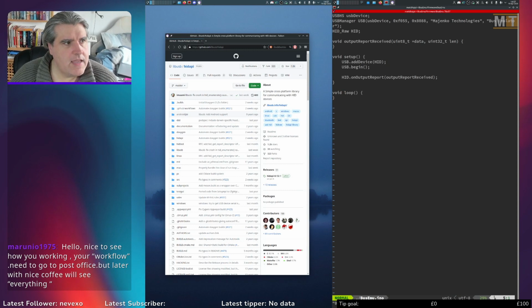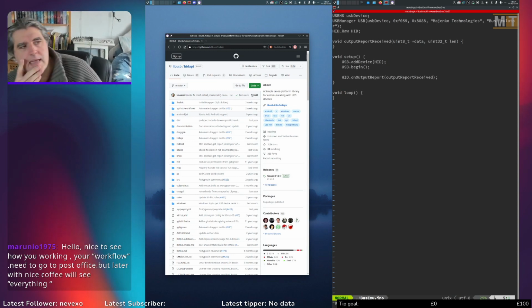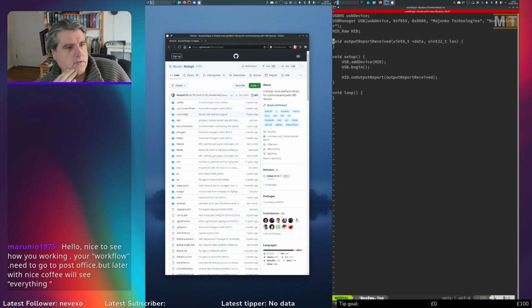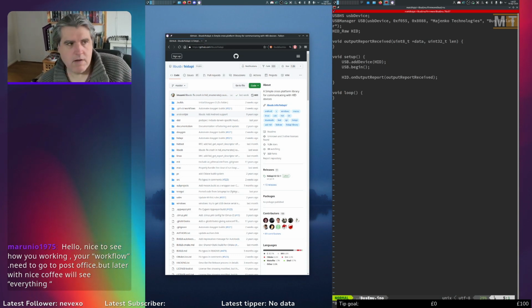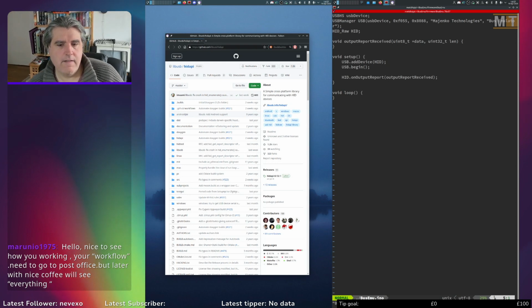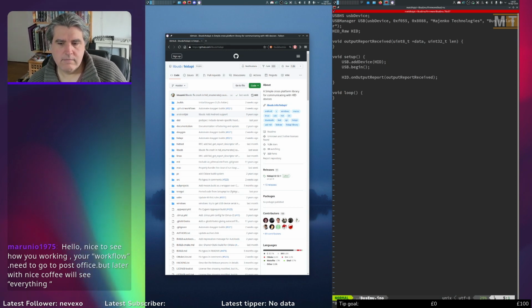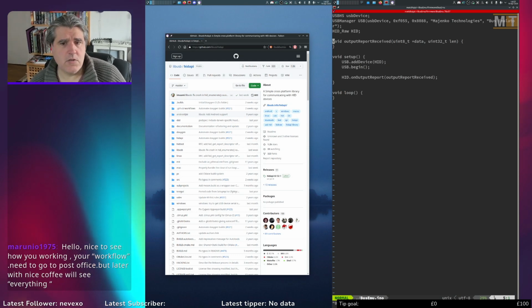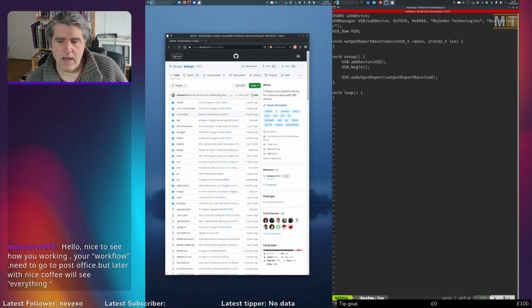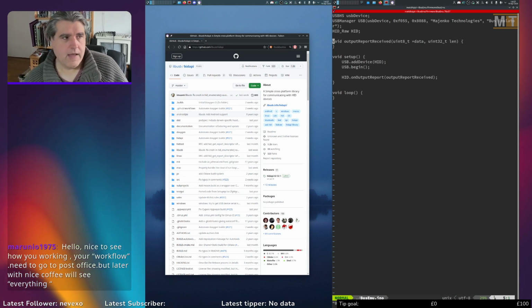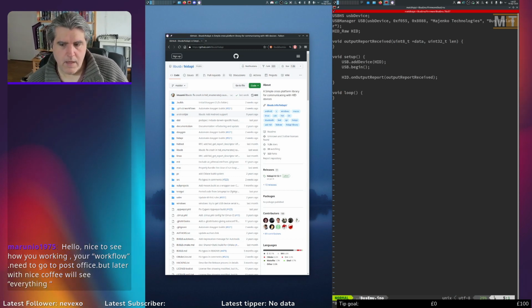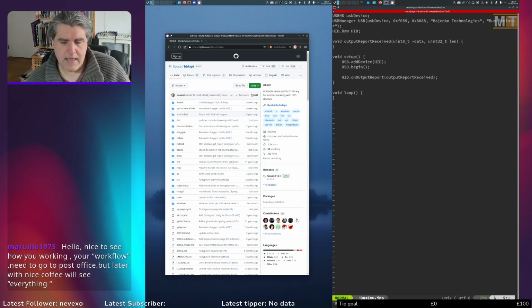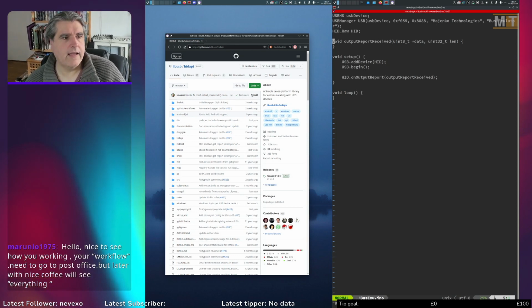So what I'm thinking might be, if I were to have a 2-byte report, keep it very simple, actually no, it doesn't even need to be a 2-byte report, a 1 or 2-byte report, where the first byte is the operation and the highest bit of the first byte is a read-write flag.